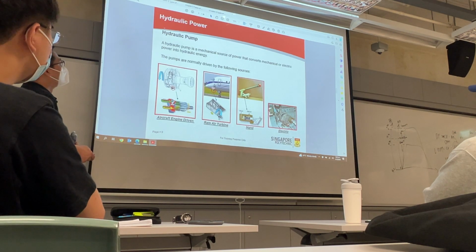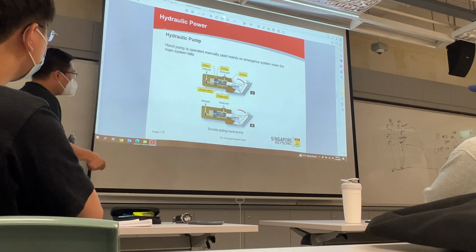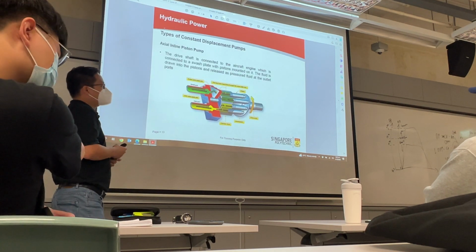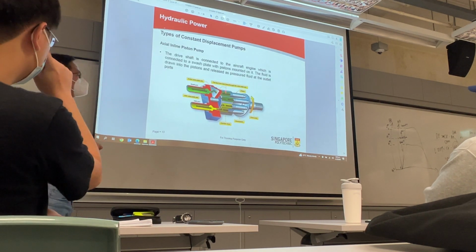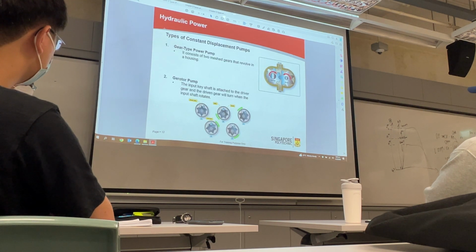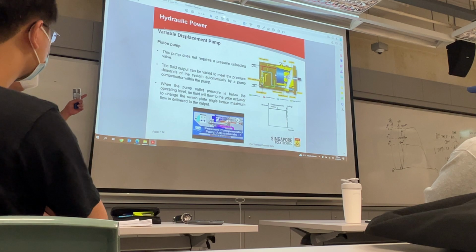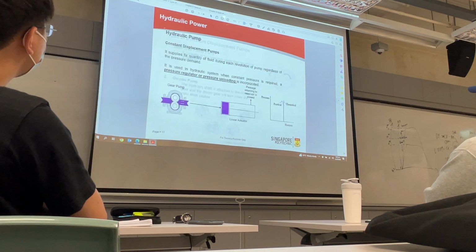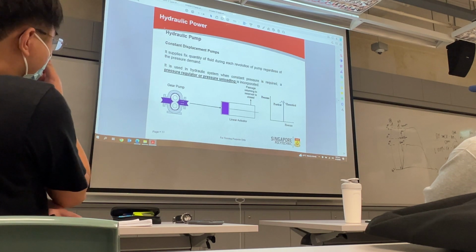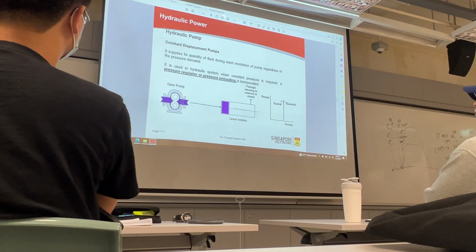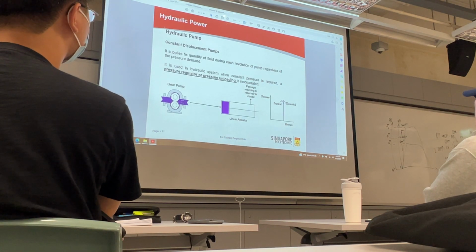Just to share, of all the pumps that we studied so far, the piston type is always able to give us higher pressure as compared to the others. That's also the reason why they use this concept in the variable displacement pump. Okay? Now let's come back to this. Constant displacement pumps always have a graph like this. What does this mean if you forgot in the lab?